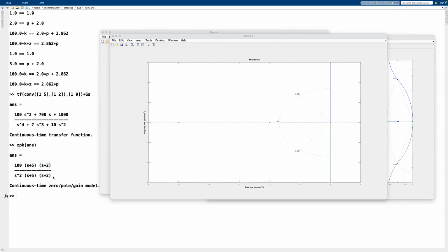And in closed loop, you will end up with these closed-loop characteristic polynomials. If you choose k to be anything, you will end up with sinusoidal waves, because it's on the j omega axis. It's a pure sinusoid. If k is equal to 0, you will have a parabolic output, because the inverse Laplace of 1 over s squared is something like that.